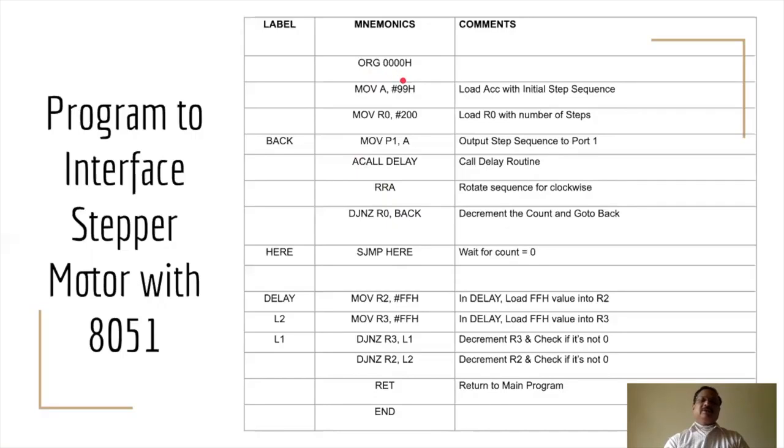There are different assembler directives like DB, define byte, DW, define word. Those are used for defining the variables. Then EQU for defining the constant. These are used as directions to the assembler, because we use assembler to assemble the assembly language program.